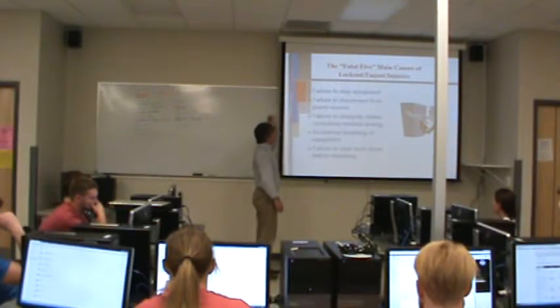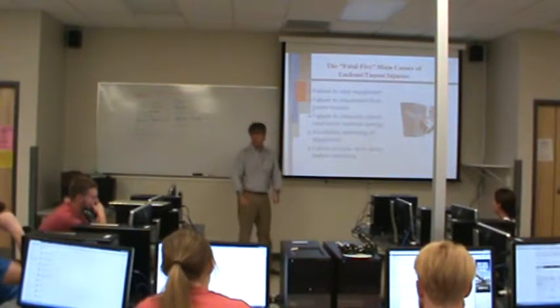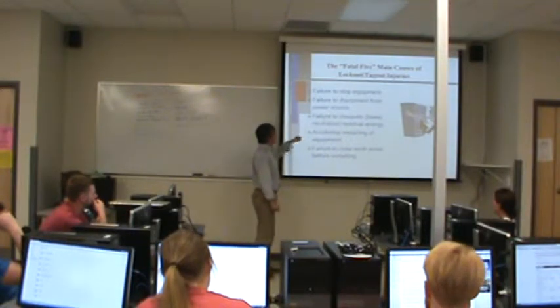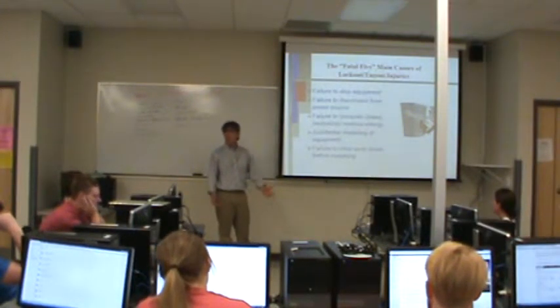Fatal 5, main causes of injuries. Failure to stop the equipment. Oh, I'll just make an adjustment while it's running. Failure to disconnect from the power source. Okay, I'll work on it hot, no big deal.